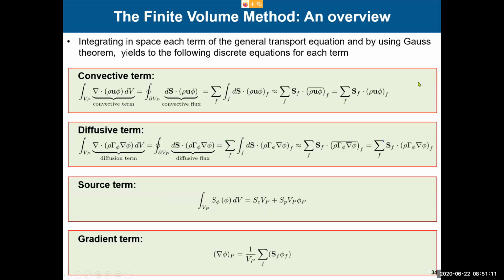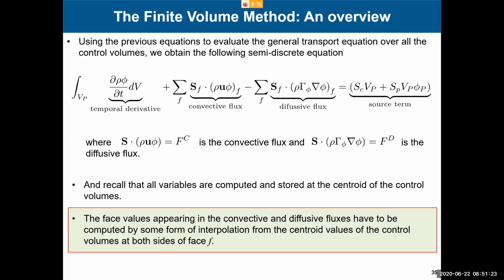So at the end, you will have these equations, and then you can just convert them into your program, whatever you are doing, and do summations along all your data, your mesh data structure. So now the big question is that we have all the fluxes at the faces, but we compute them at the cell center. So we know it at the cell center from the initial conditions or the previous iteration, whatever. So how do we interpolate these values from the cell center to the face center?